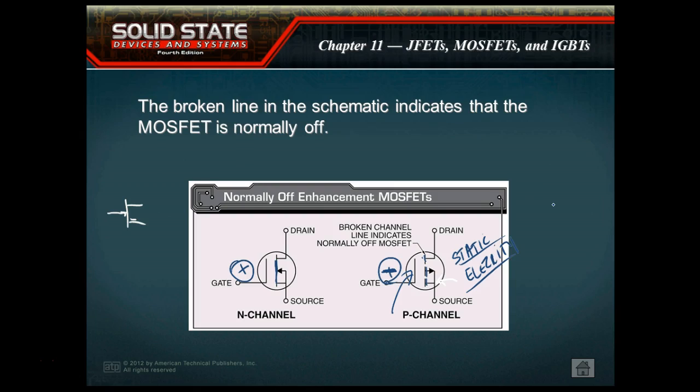If you're going to work with memory inside a computer, all your memory is made out of MOS transistors, which means these guys are very susceptible to damage by static discharge. And a lot of times you have a static discharge, people, and you do not even know it. But just taking very few safety precautions, and it's not safety because you're going to hurt you. It's safety because you're going to hurt your device. Very few safety precautions, you can work with these things for years and years and not have any problems at all. So I'll show y'all that.